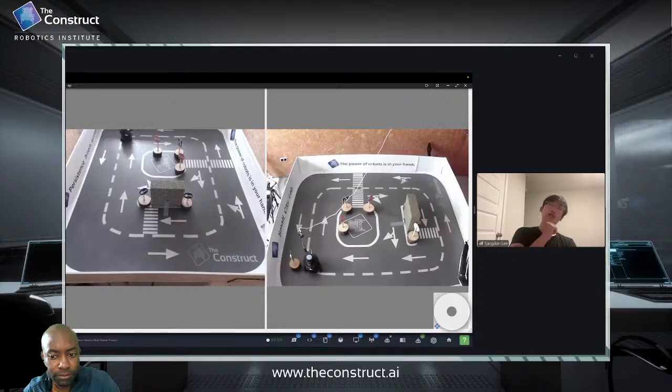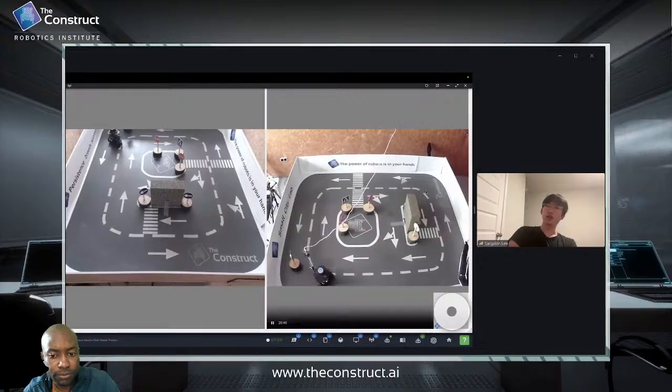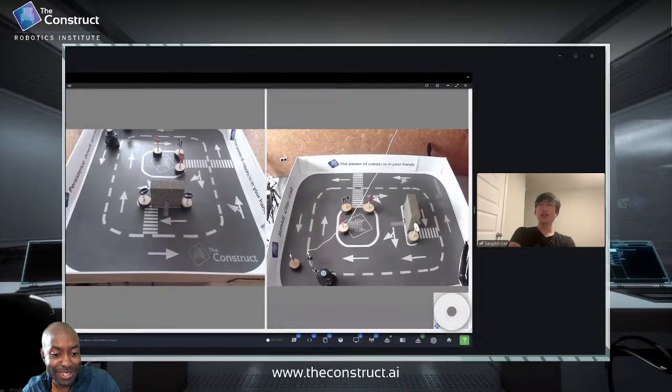But the distance I chose was based on when it goes front, and when I tested, it doesn't really exceed a lot. But I guess what you're saying is when it's at the middle right here, next to a stone thing, it might crash into it. Yes, it might crash into it when it reverses. Yes, that's why I'm asking. So I should definitely add that logic for the back range. I should add the distance to move logic so you make sure it's safe when it backs off.